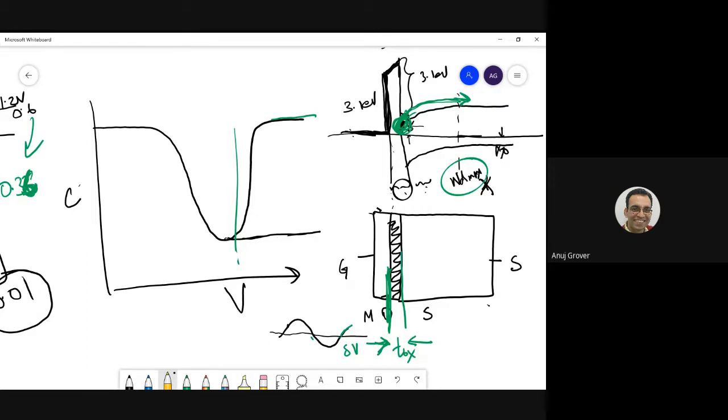So now what happens when we are talking about, let us say, high frequency? At high frequency, there are electrons over here which want to move out. But what is the curve? Something like this. So when the voltage went negative, the electron starts to move out, but before it actually moves out, before it just reached here, yet what happened? It became positive. So this electron came back here.